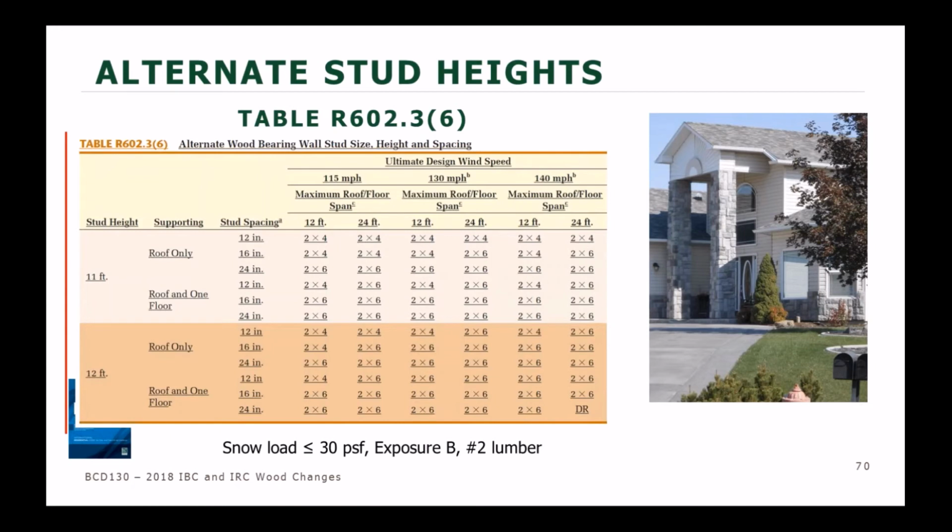And if I am in an area with a snow load of, say, 35 PSF, then I am back in that gray area where wall bracing allows me to have the taller studs, but the story height section of Chapter 3 basically tells me for my gravity loads, now I need engineering, which is very different than anything else we've had in the IRC.